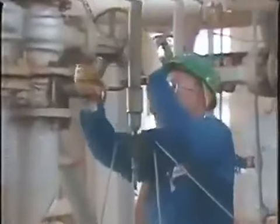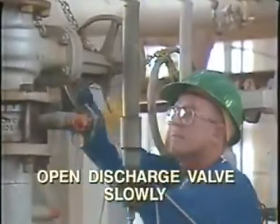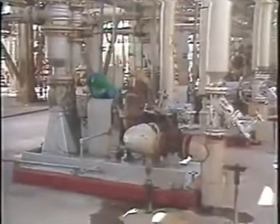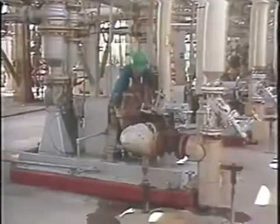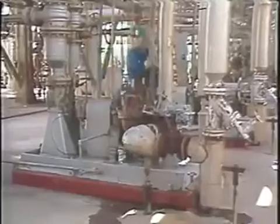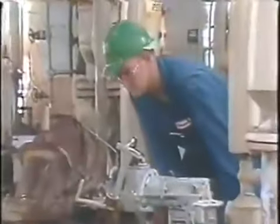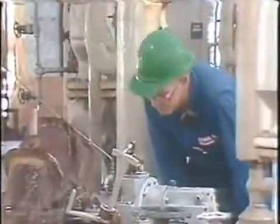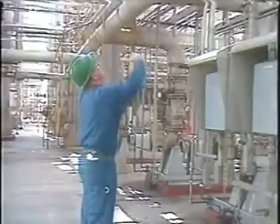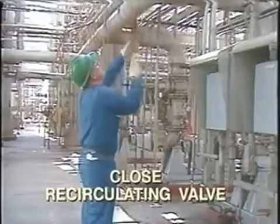After the driver has started and is operating correctly, slowly open the discharge valve. Observe and listen to the pump and driver to be sure they're operating correctly. Check that the discharge head is normal and for excessive leakage around the packing box. Adjust the sealing liquid valve to be sure that the sealing liquid is flowing at the proper rate. After you're assured that the pump is operating correctly, close the recirculating valve.